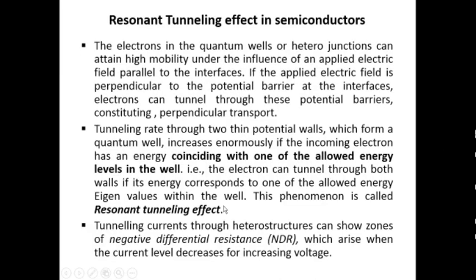Now let us consider what is meant by the resonant tunneling effect in semiconductors. We know that electrons in quantum wells or heterojunctions can attain high mobility under the influence of an applied electric field parallel to the interfaces. But if the applied electric field is perpendicular to the potential barrier at the interfaces, electrons can tunnel through these potential barriers, constituting a perpendicular transport of electrons.